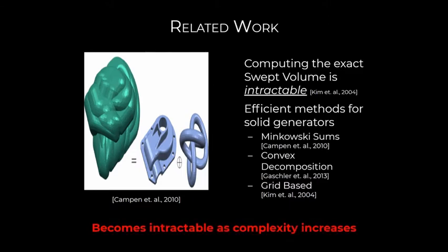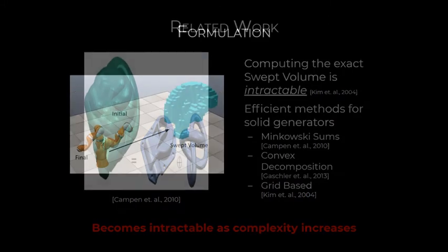In our work, we chose a learning approach with deep neural networks instead of iterative generation to speed up the process. The network we use learns the swept volume problem as a classification task and approximates swept volume directly from the configurations of the robot.